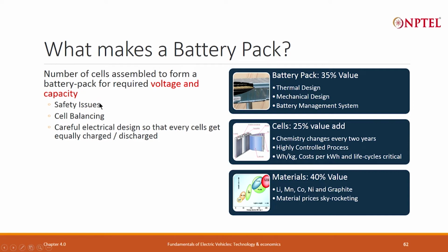The issues that you need to deal with is first the safety issue. Now, a cell is a cell, it is given. A cell in itself is never used, it is a pack which is used. So, immediately you look at the safety issue. The second very important thing is what is called cell balancing, and I will come to cell balancing in a short while, because there may be two cells in parallel, but they may not be charged equally.